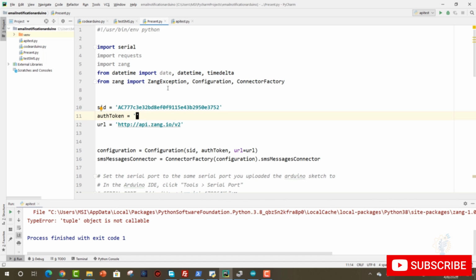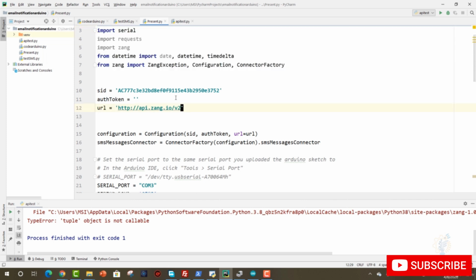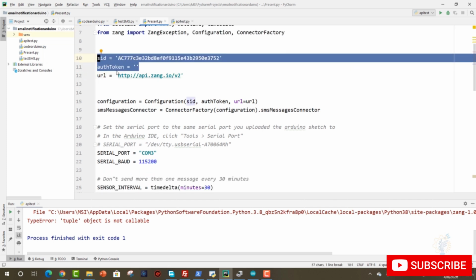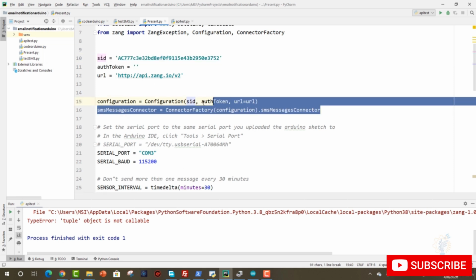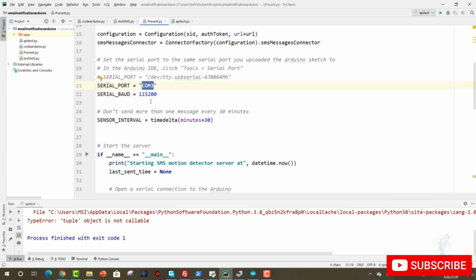But before that, let's make a quick summary for everything. Here we have imported libraries that are necessary. Here we have imported the credential information from the API website for sending SMS. These two lines are from the API website to configure the SMS send function, and these two lines for initiating the baud rate and the COM port number.